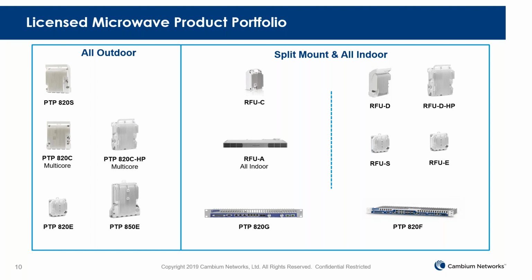If you have a high performance parabolic pencil beam kind of antenna, the effects of the proximity to the other radio reduce. But if you have more of a sector or a wide 3 degree beam width, it may affect the radio itself. So it all depends, but the rule of thumb is it should at least be 5 to 10 feet away.